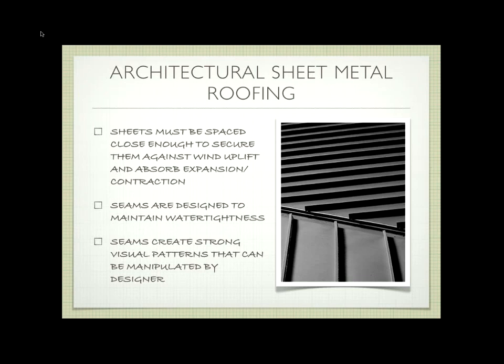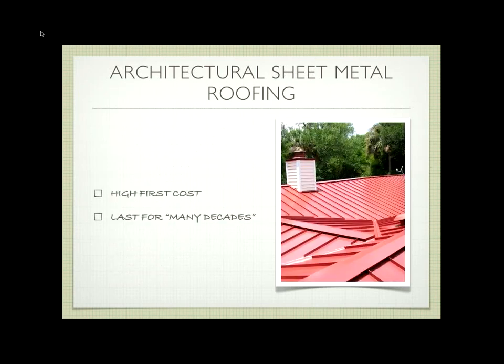Okay. The other thing is that seams do create a very strong visual pattern on the roof, something to be aware of. Okay. Generally, they have a high first cost, and the book says they last for, quote, many decades. Yeah. Could you be more vague? You know, basically, a roof like this is going to last as long as the finish lasts that protects it from the weather, right? Or as long as you don't ruin it somehow by walking on it or putting a nail through it. Okay? So it can be a really long-lasting, efficient roof.